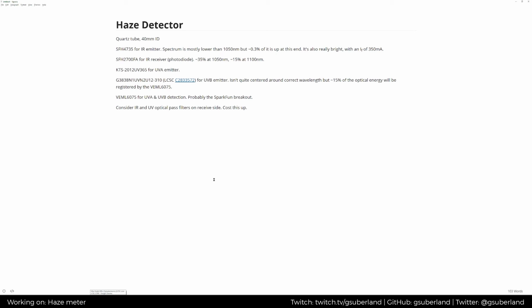Obviously, the white LED and the light sensor there. What I will probably do is just go for a very generic white LED, probably something that's half decent, with a decent broad spectrum. See if I can find something that's marketed as a SAD light or something, with a really nice CRI, a high CRI LED, and then use that, because a nice broad spectrum LED is good for getting a good detection response.